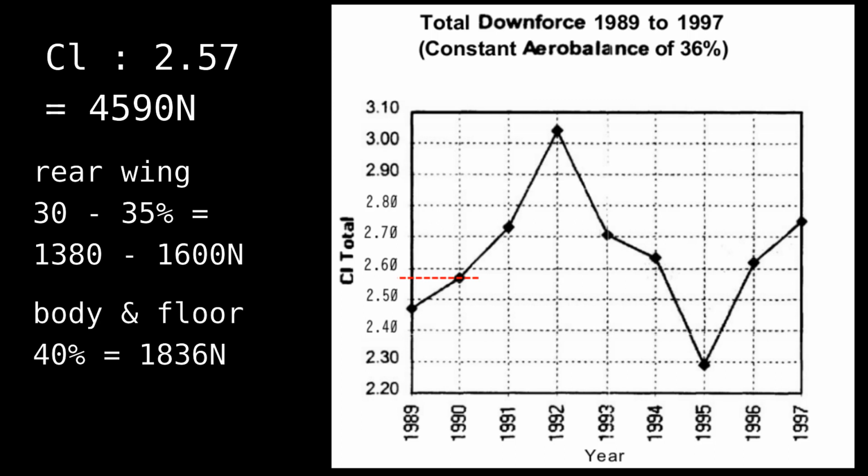We don't know the ride height. I use the 21mm at the floor's leading edge with 0.2 degrees of rake, like I always do, with the paper stating 1836 newtons produced by the body and floor. The remainder is the front wing with a maximum of negative 1154 newtons. However, this isn't including the positive lift of the wheels, which is substantial.